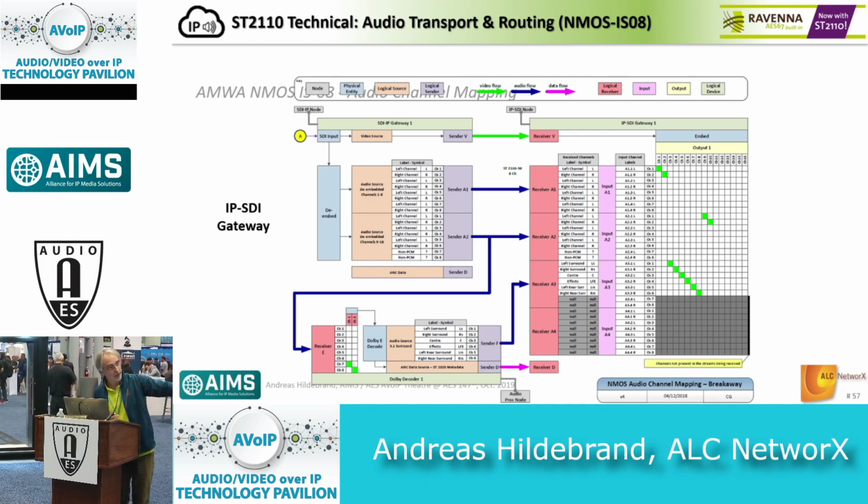So it's routed to a different device, a Dolby E decoder actually, and it takes the 2 channels of Dolby E information, runs them through the Dolby E decoder, and sends out the decoded audio channels as independent audio channels in one AES67 or -30 stream, which can be received by another receiving point of whatever the processing device is.